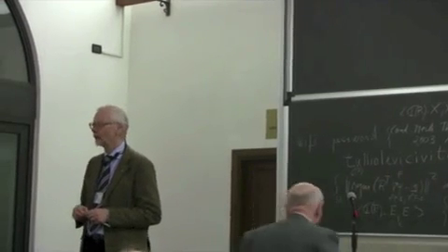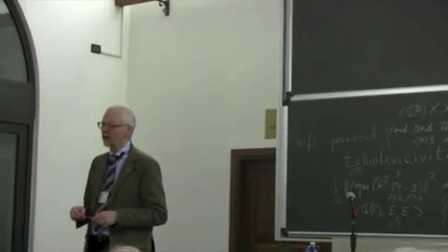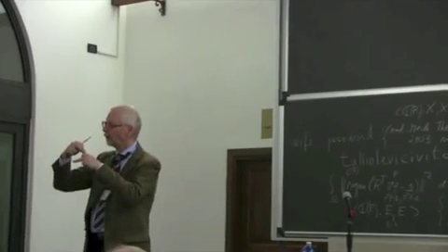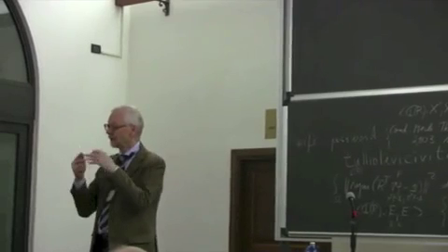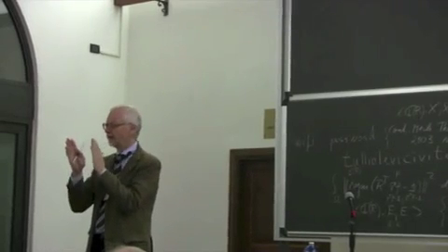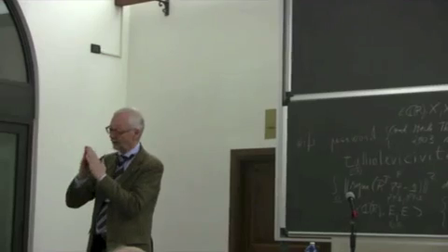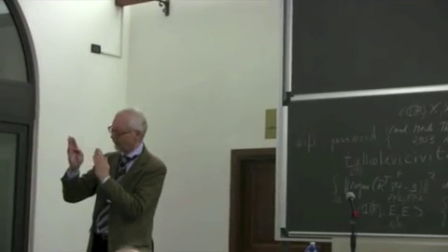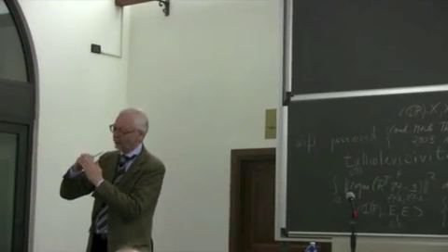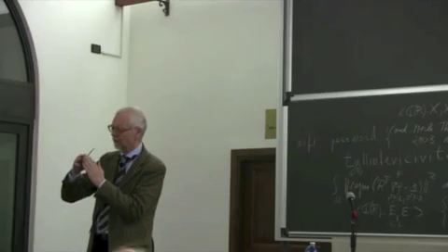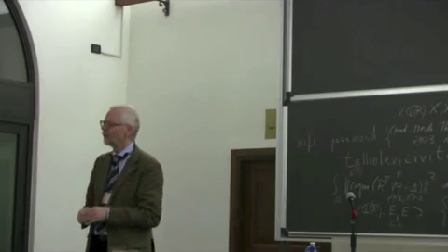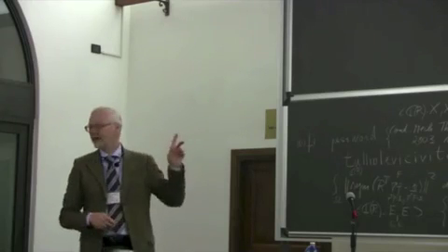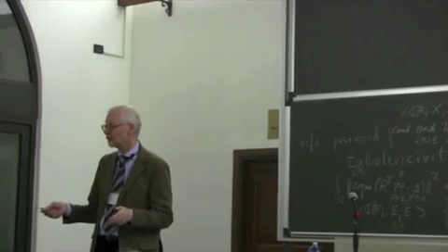Normally we use coarse meshes, but we use special crack tip elements. We put a rosette of finite elements around the crack tip, and they are 8-noded elements. They are collapsed. One of the sides is collapsed to 1 point. Therefore, 3 points are in one, and the midpoints are shifted to the quarter point position, and these elements build up the 1 over square root r singularity exactly. Therefore, we can have these results with quite coarse meshes.